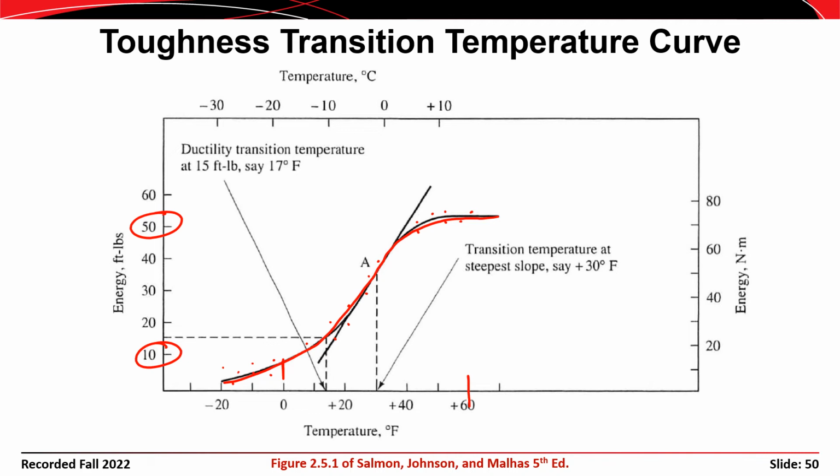So that's important to us. We need to know what that range of toughness is. If it's a bridge type structure that's erected in Alaska, then it's important to know that our material might not have the same toughness in the winter as it does in the summer, and it might mean that that material should be excluded for use in bridges in Alaska. But that same material might be just fine in Puerto Rico or in Florida. So anyways, toughness is also an important measure. We use Charpy V-notch toughness testing, and the toughness of the material is a function of the temperature.